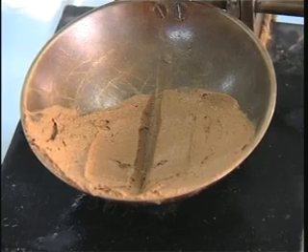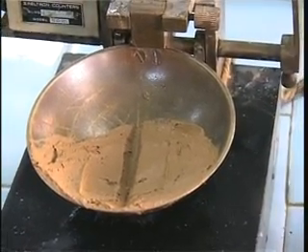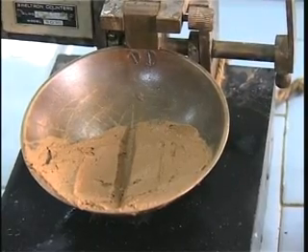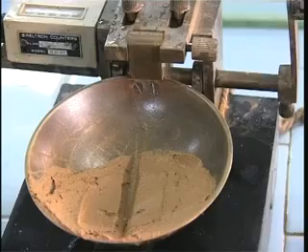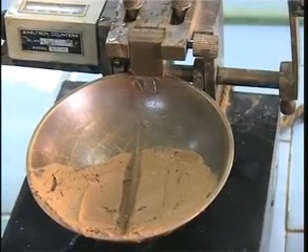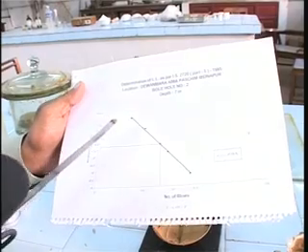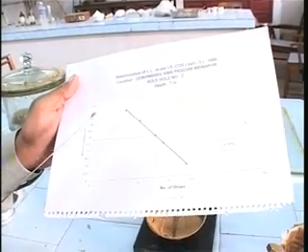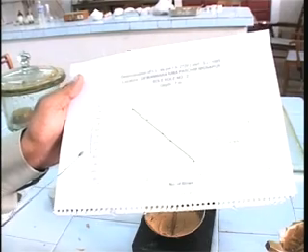And what we have to do is keep on adding a little bit of water to the sample until we get the groove to close by 12.5 millimeter exactly on the 25th blow. And for doing that, we are going to go on adding water, and we are going to plot the number of blows required for the closure of 12.5 millimeter in this type of plot.